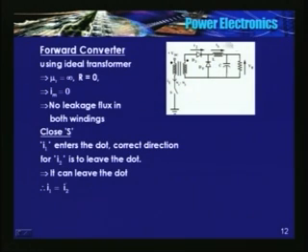There is a path for the load current or inductor current. Since there is no leakage inductance here and no magnetizing current here, the circuit works satisfactorily. A circuit can work, but there is always a finite magnetizing inductance. The ampere turns required to establish the flux in the core is finite, and that has to be continuous.